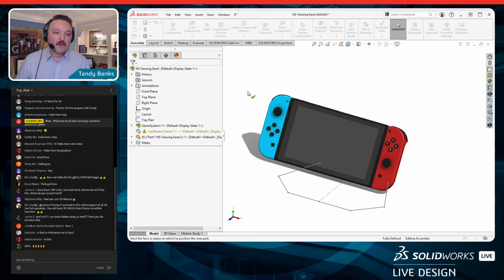And that's one of the default settings within SolidWorks, is that when we create new components, they're going to be saved as an internal data set within the assembly that I'm working from. Now a little later on, I'm going to kick that out so that it's going to be its own SLDPRT file. It would be its own solid model part file. But for right now, I'm going to do my design work and have it all internal to my assembly.